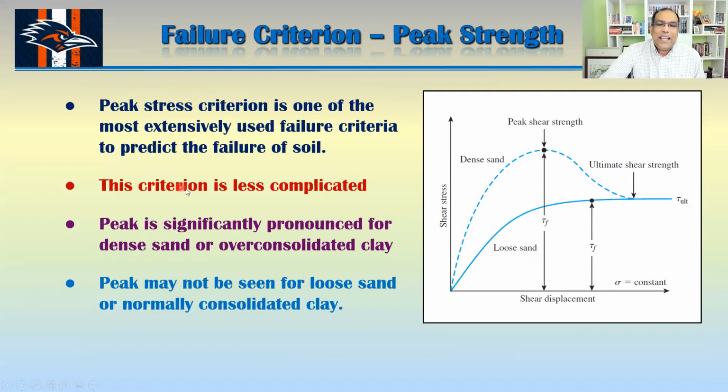So this criterion is less complicated. Peak is significantly pronounced for dense sand or over consolidated clay. For loose sand and normally consolidated clay, it doesn't show the peak that well. So that's the criterion we use most of the time.